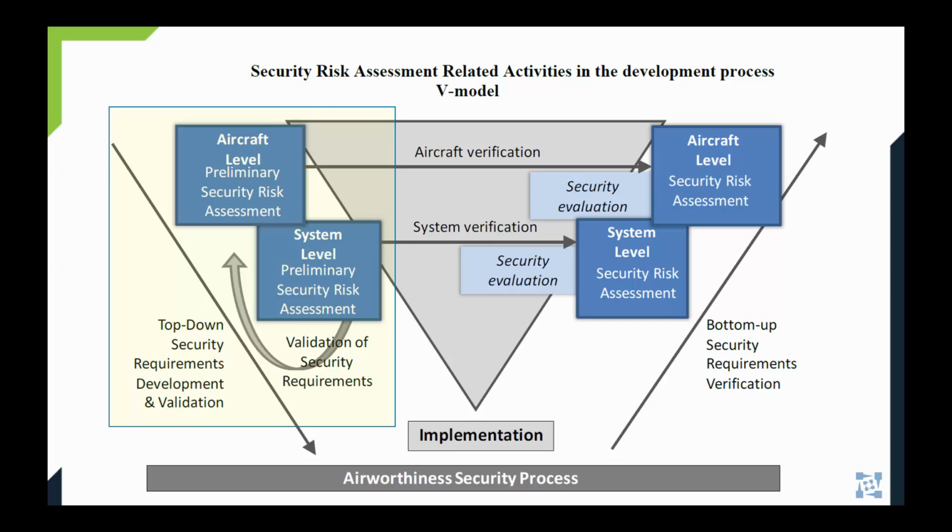This process is very well defined in DO-178. The key difference here is that we are adding a security process which is well defined in DO-326A. So know that there is also a security risk assessment to be made. If the security assessment level requires threat mitigation, it must be designed into the system, and a test to verify the effectiveness of the solution against the threat must be defined.